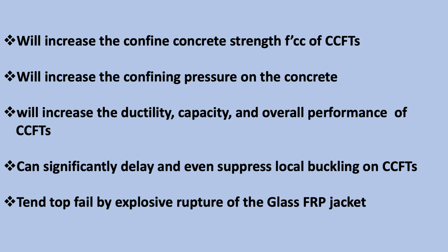Studies have shown that the added confinement from the fiber reinforced polymer jacket or wrap will increase the confined concrete strength of the circular CFTs, will increase the confining pressure on the concrete, will increase also the ductility, capacity, and the overall performance of circular CFTs.